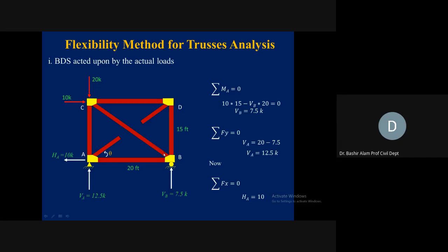So this is how we fix its direction. Its vertical will be downward directed and its horizontal will be rightward directed. So this will balance that tensile force in this member AB. Means BC is also under compression. And very easily by putting the summation of Fx equal to 0 and summation of Fy equal to 0, we can find out the BC force. And this will give you the capital P values.